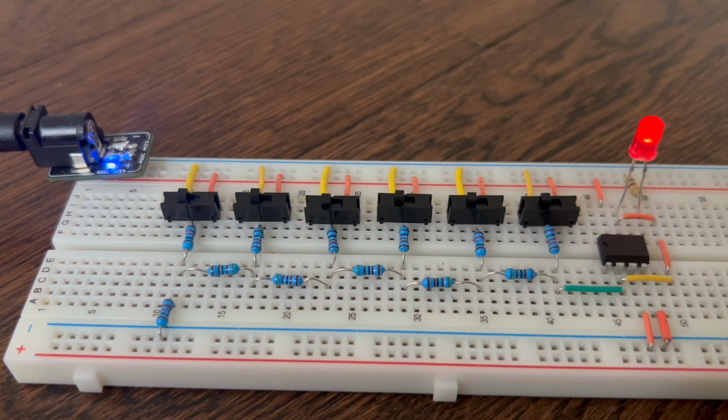The chip features a voltage swing that is constrained to be 1 volt less than the high and low voltage rails at its two ends. This limitation exists due to the presence of a buffer within the op-amp circuitry. In practical terms, the LM741 op-amp's limitations become evident when the high voltage rail is at 5 volts and the low voltage rail is at 0 volts.